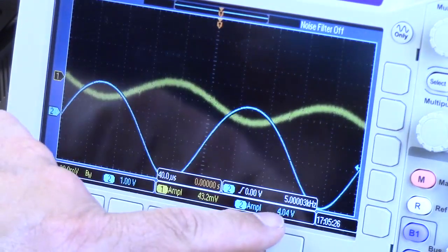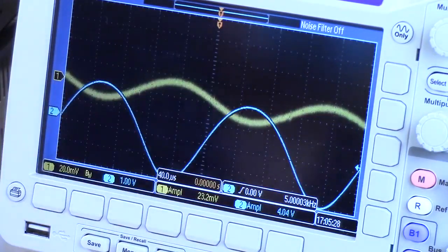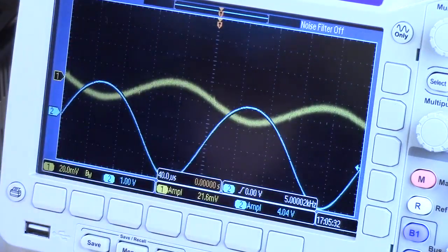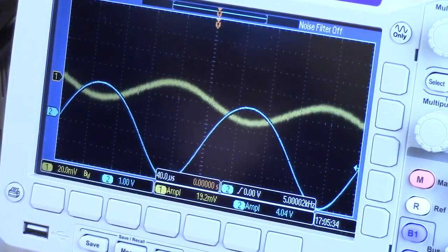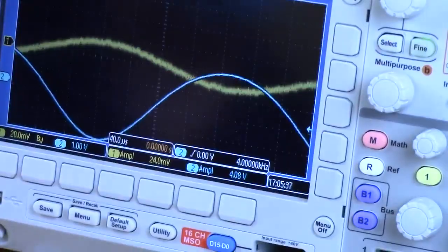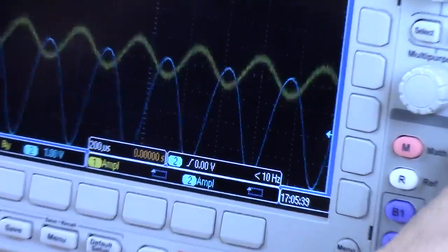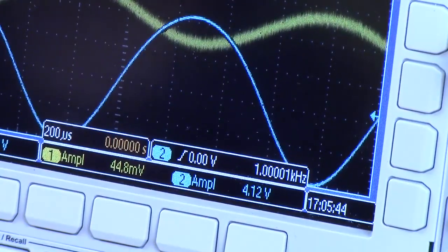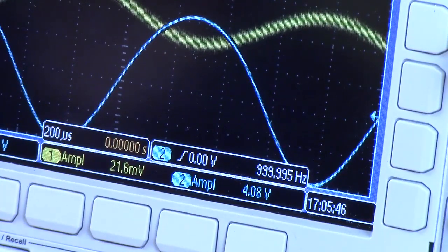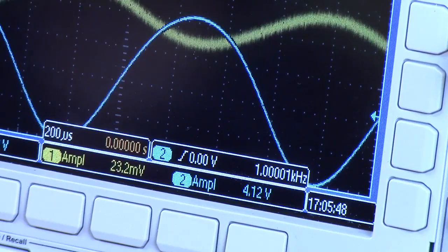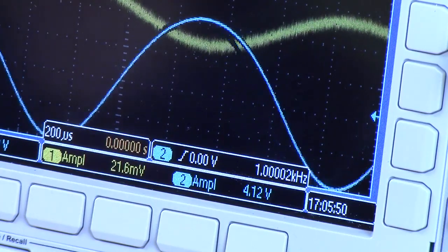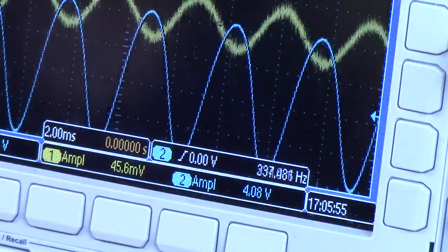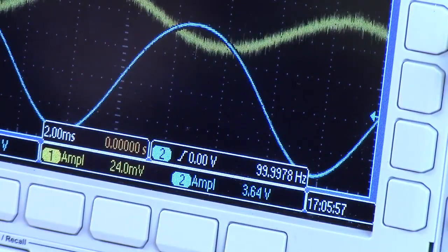We now have an amplitude of 4 volts peak to peak, and we're going to turn that frequency down until that reads 2.8 volts peak to peak. Right now we're at a frequency of 5 kilohertz. We're going to start to bring the frequency down, and let's adjust to keep the waveform completely on the screen. Right now we're still at around 4.8, and we've dropped below 1 kilohertz. Okay, now we're just starting to come down.